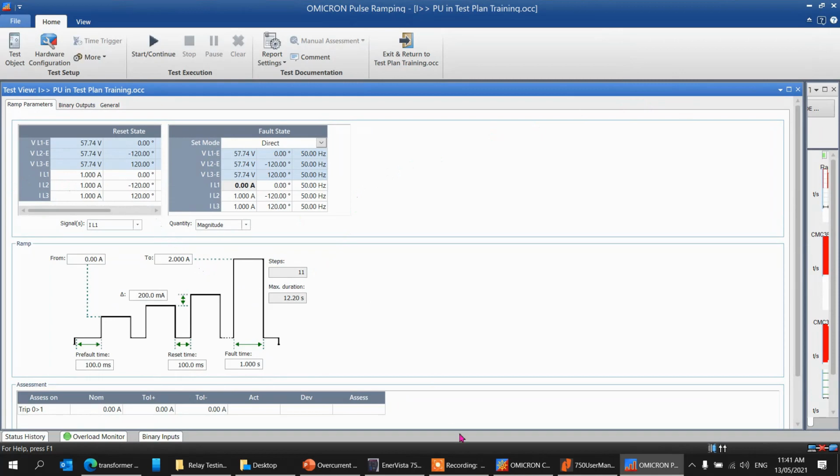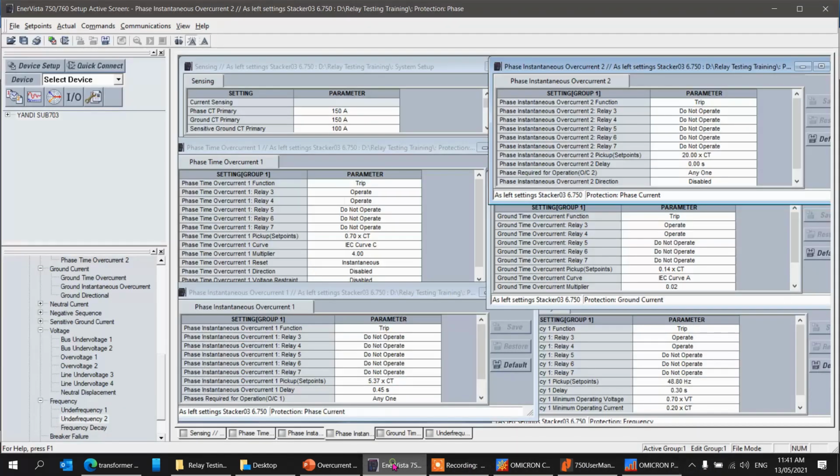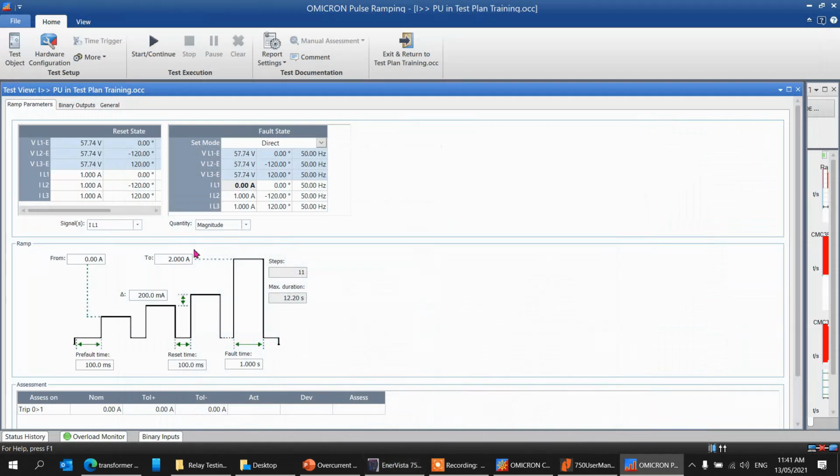So yeah, you have our setting. I think the setting is, let's say, 5.37. So you have to start here, below the IDMT. Let's say 5. Oops, no, that's your reset time. So it should be less than the IDMT. Let's say below 0.7, so 0.5. Equal magnitudes. Okay, and this one should be around 5.